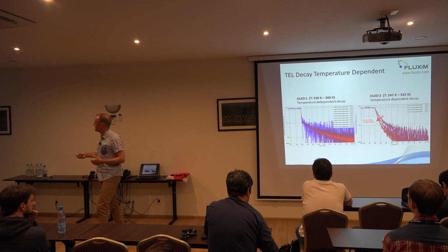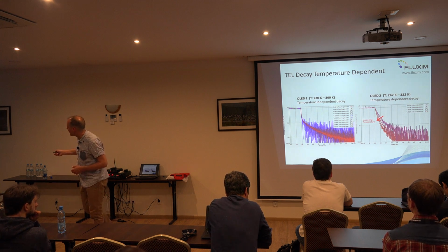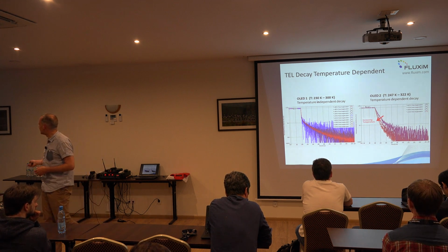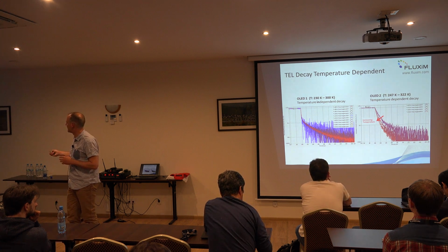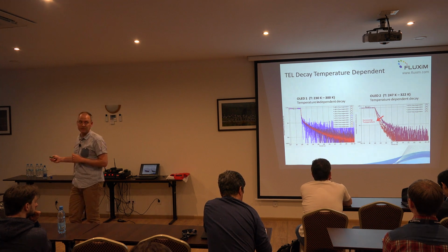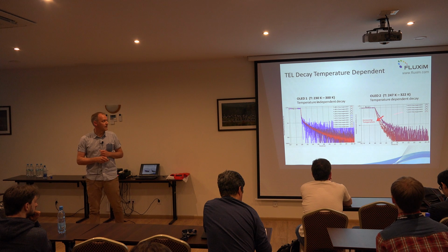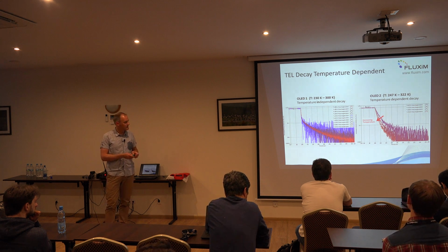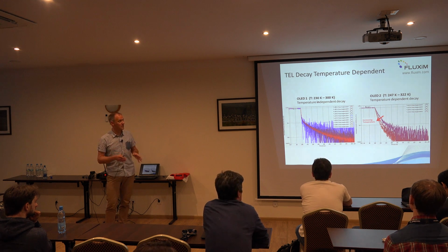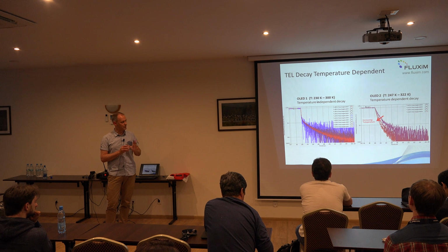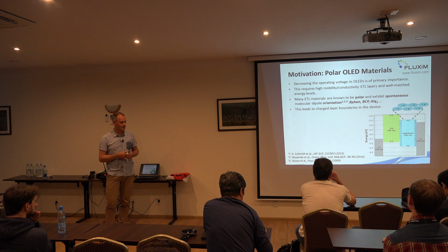we see a distinct change. So the decay of electroluminescence changes. This is kind of TADF-like, where at high temperature, we have a faster decay than at low temperature. Yeah. So you can get some systematic data with the real OLED. You're not doing an experiment in a photophysics optics lab, but just directly OLED, put it in a small cryostat chamber, and you already get a lot.